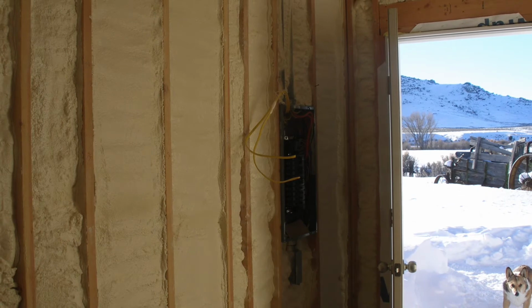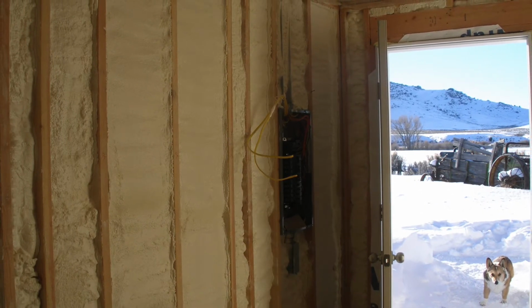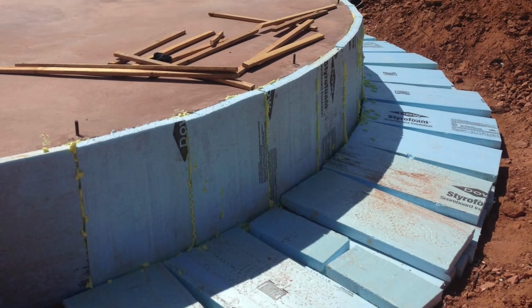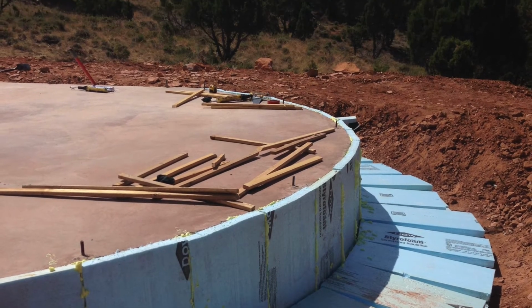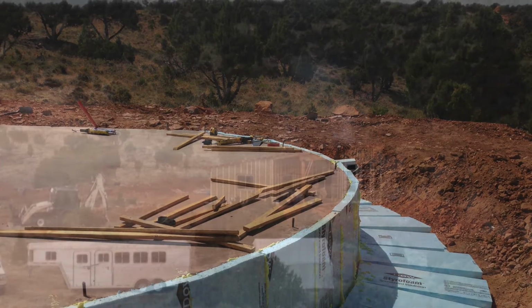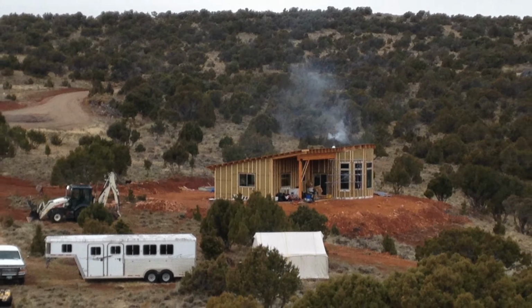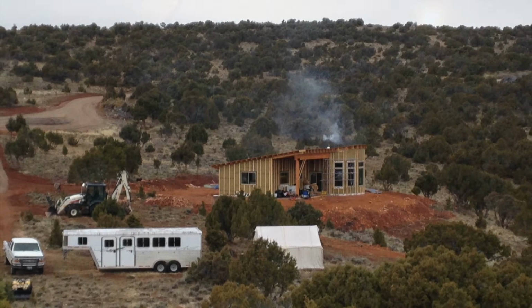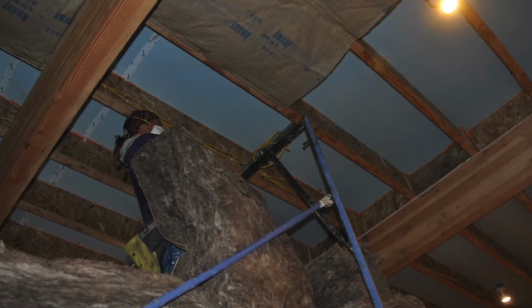Some things to consider also about foam is it has a very large environmental cost in its production. So you may want to look at other options based on your ethics and also your flammability. The foam can burn and can be dangerous in high fire areas. So we didn't put any foam on the exterior of our building, though it would have been a great exterior insulation because we're in a high fire danger area. In our ceiling, we used a combo of a foam channel and fiberglass insulation.